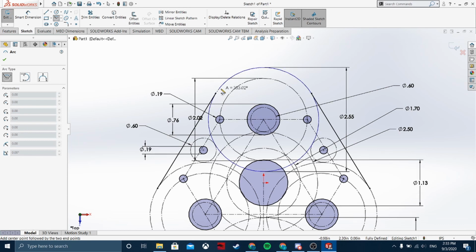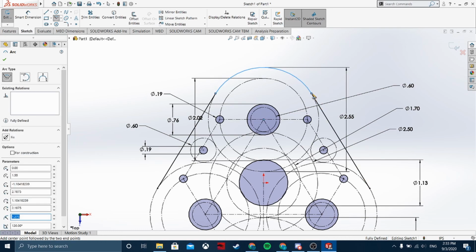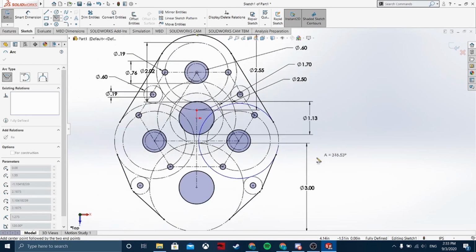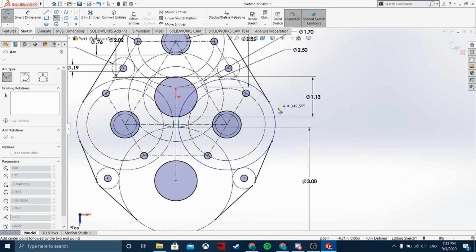Make sure the outline is facing towards where you want the arc to be. And once you hover your mouse over the second endpoint, make sure the line is highlighted. If it's not highlighted, it's not going to close the line. So just click on that once the line's highlighted, and repeat that, right, until your arc is finished. So I'm going to fast forward this.